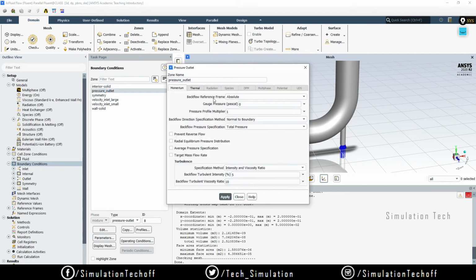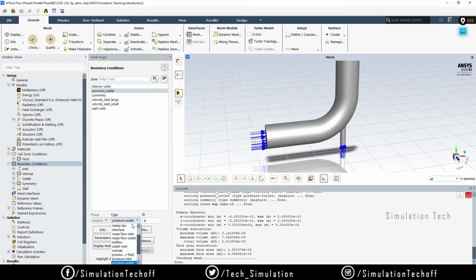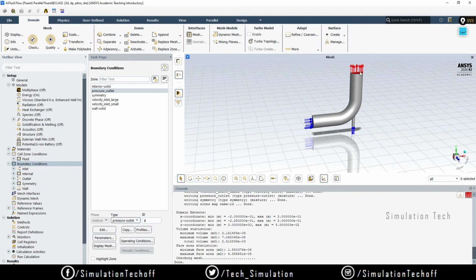The same thing. Change the type to pattern. Otherwise I will use the same thing, or else you can simply change from here itself, that is outflow, that is outlet flow, and give the flow rate as 1. So when you say it as an outflow, whatever velocity comes inside will go out from that particular region. So it's up to you. So just follow whatever it is.